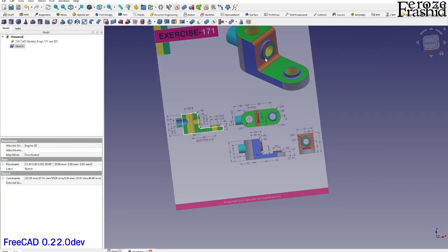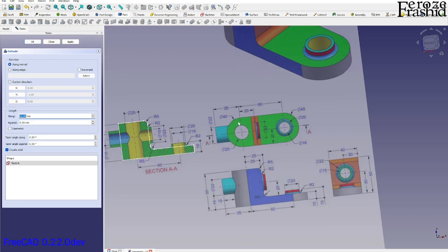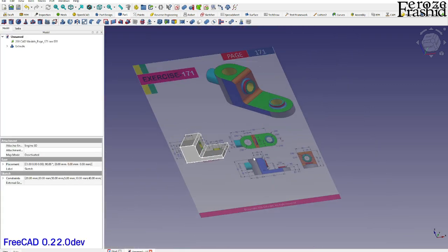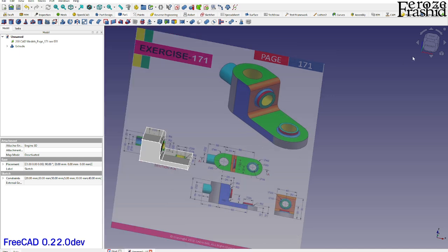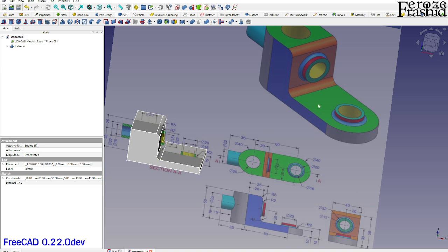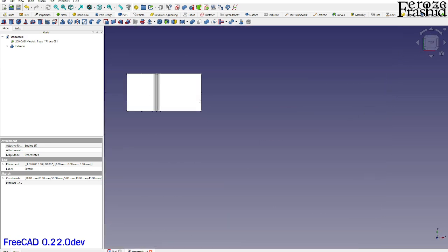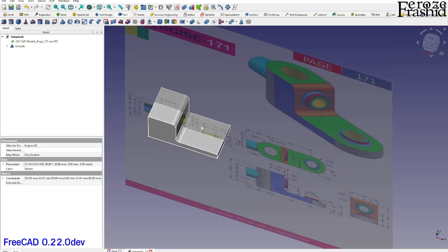And that's our first sketch. So this is this, and I want to extrude that for this length, which is 40. Let's say 50, and I want to go symmetric on this. Now I was thinking maybe I should build it ground up, like draw a slot and then draw a half slot there. So that would be another way to do it. So it would be 2 sketches, and I'm going with another 2 sketches anyway.